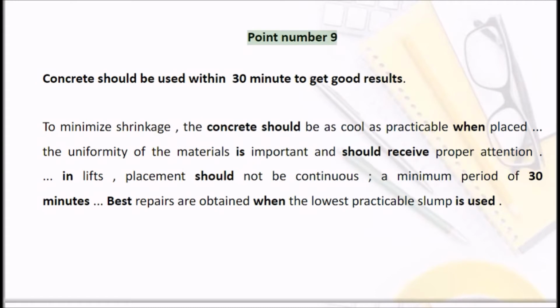Point number 9. Concrete should be used within 30 minutes to get good results. To minimize shrinkage, the concrete should be as cool as practicable when placed. The uniformity of the materials is important and should receive proper attention.